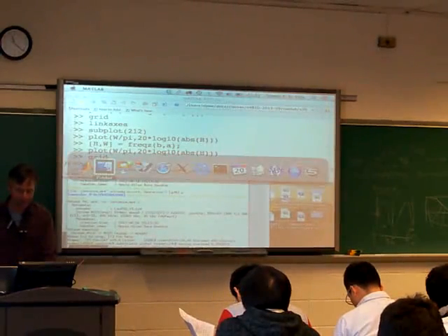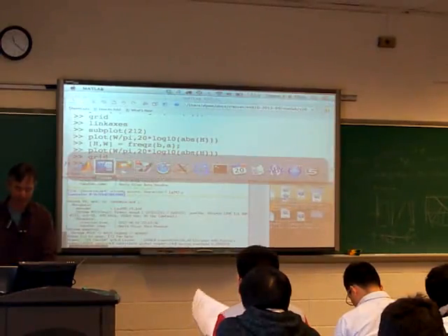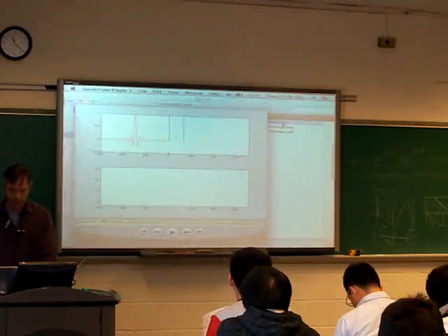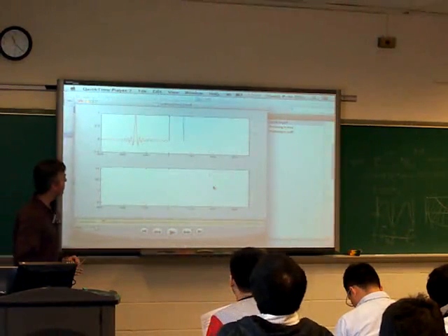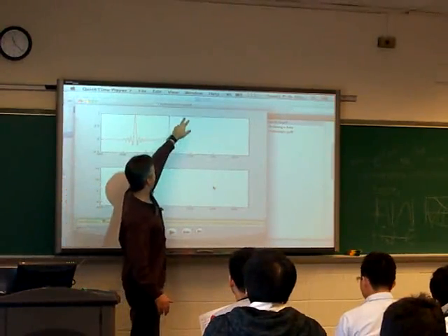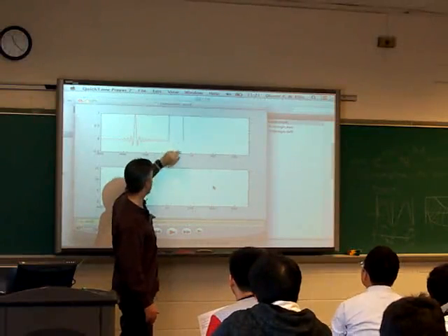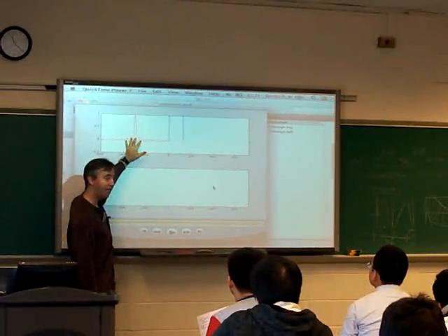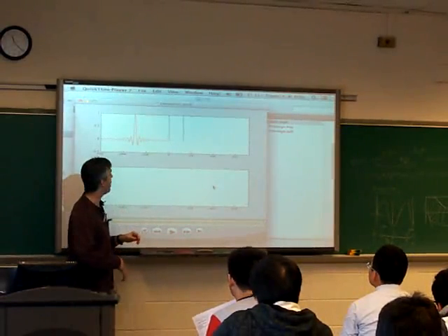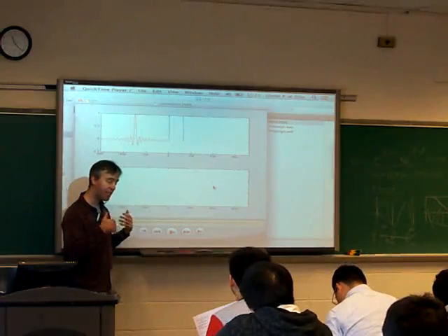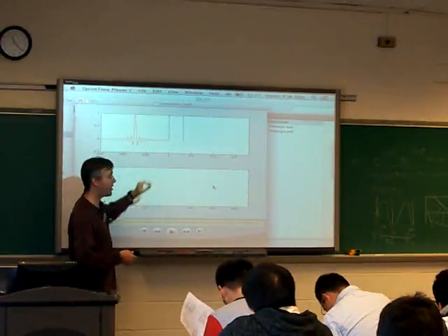In fact, no, I put it together in MATLAB and then I converted it into a movie, so we can just look at the movie here. What this is here: here's the ideal frequency response, the step function. Here's the Fourier transform of the rectangular window in time. And what we're saying is the actual effect, the resulting frequency response, is the convolution of these two things.